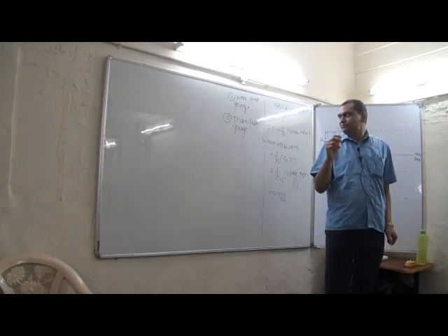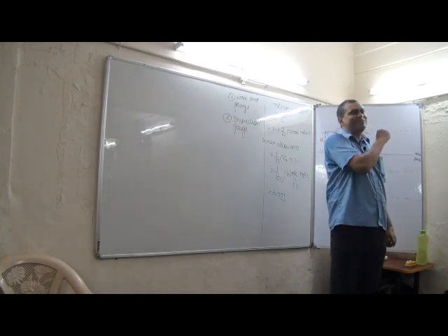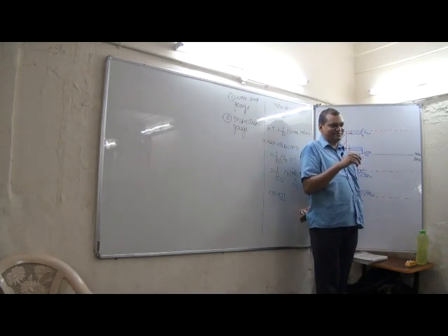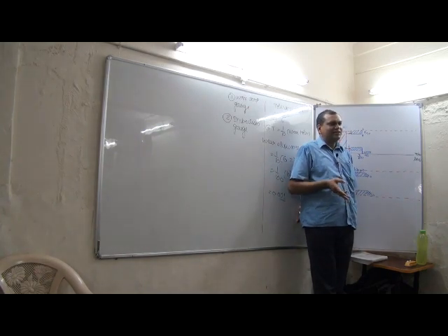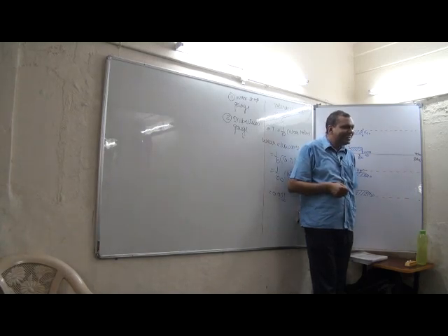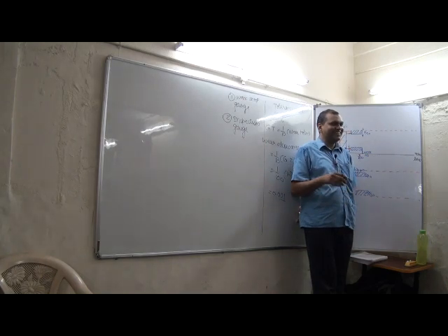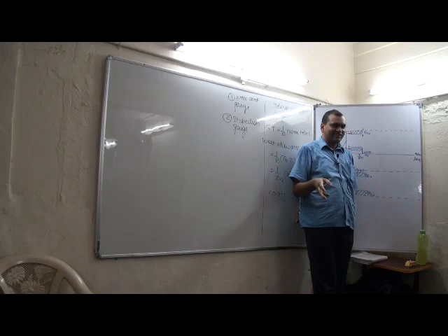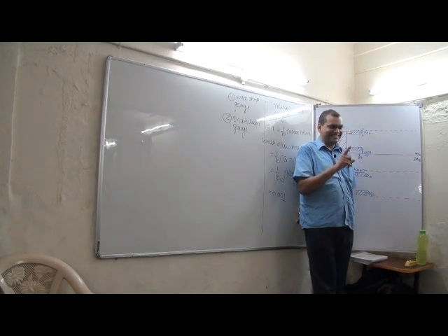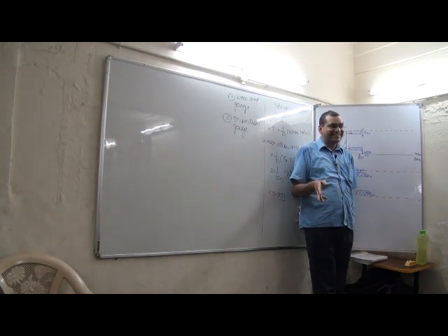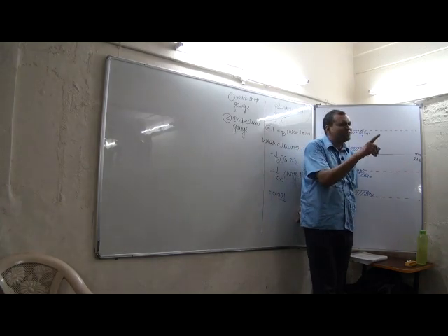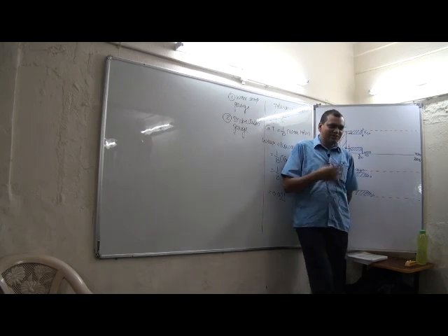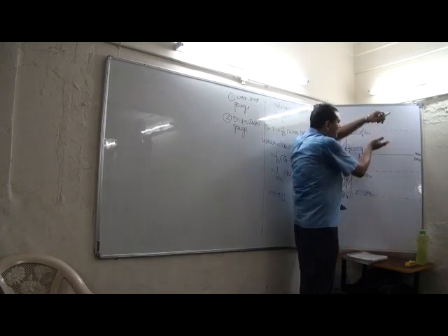So, philosophy of inspection department. What is the philosophy? Workshop department, what is the philosophy? We will not produce anything defective. Inspection department says there is already a lot of effort that has been taken to make the product, so no good part has to be rejected. Workshop department says we will not produce bad parts, but there will be tolerances, and some good parts you are rejecting. Inspection department says a lot of effort, machine, material, a lot of things have gone into making this product, so good parts should not be rejected. Understand? So due to this philosophy, the tolerance on the gauges will be away from the work tolerance.